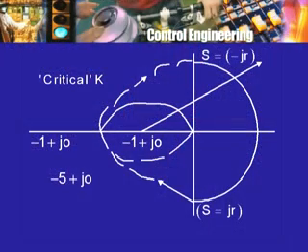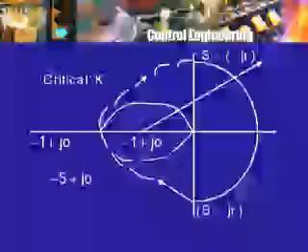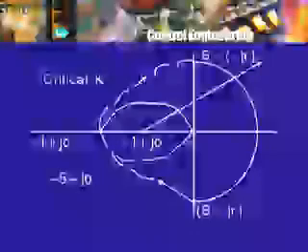Now that is a little difficult to consider here. Let us say this was the polar plot, the gain has not changed, but the amplifier has introduced a phase shift. For example, the integrator. The ideal integrator has the transfer function 1 by s or k by s. The practical integrator, however, does not have this ideal transfer function. As a result, the practical integrator will produce a phase shift not just of minus 90 degrees, but of a slightly different amount which will change with frequency.